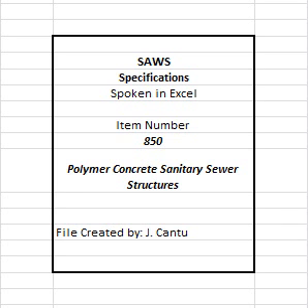5. Structure components shall be manufactured by the vibratory vertical casting process resulting in a dense, non-porous, corrosion-resistant, homogeneous, composite structure. 6. Each polymer concrete structure component shall be free of all defects, including indentations, cracks, foreign inclusions and resin-starved areas that, due to their nature and degree or extent, detrimentally affect the strength and serviceability of the component part. 7. The nominal internal diameter of structure components shall not vary more than 2%.